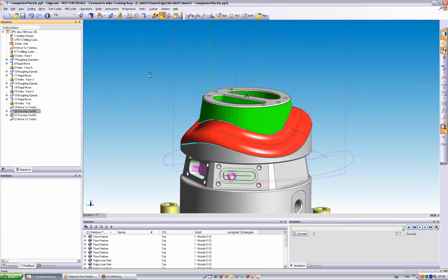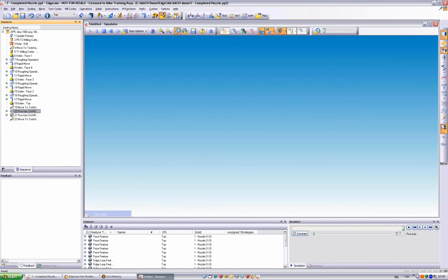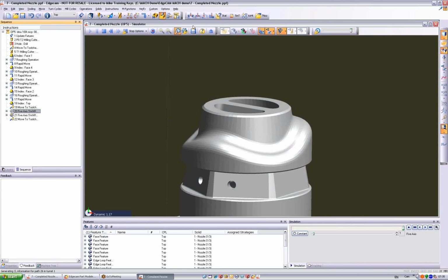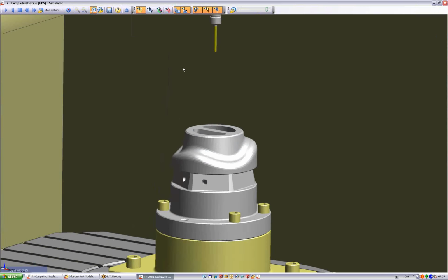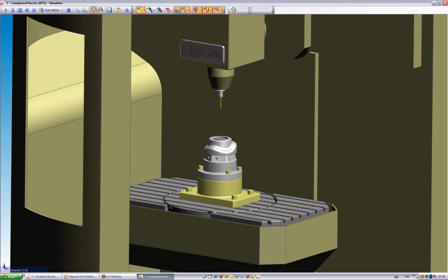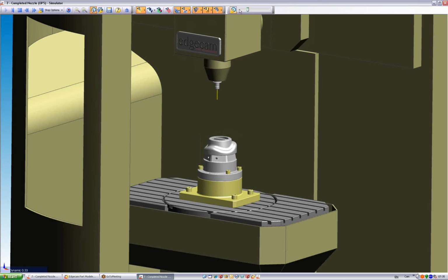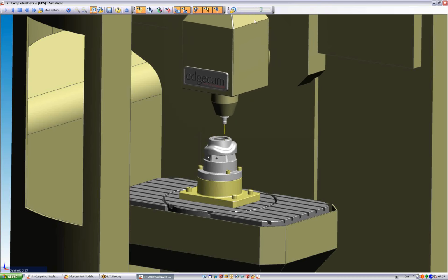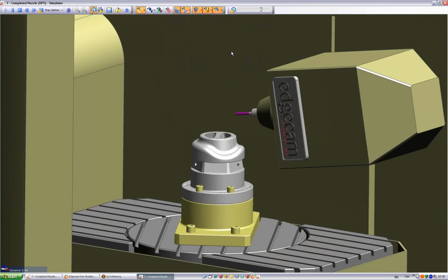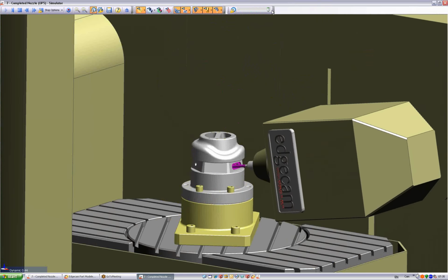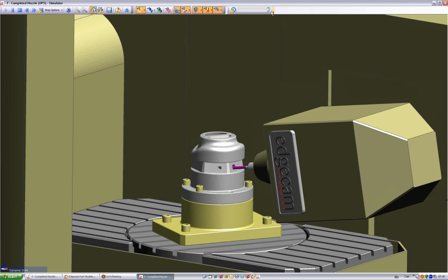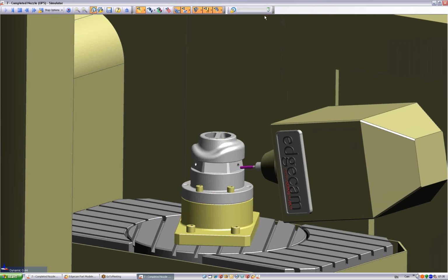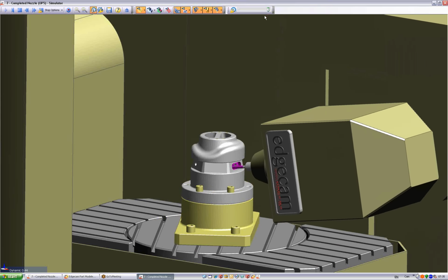And again, we'll just conclude because obviously machine tool simulation is extremely important, again, to make sure that all the machine tool members, indexing, 5-axis, drilling, profiling, roughing, all these need to be simulated, all need to be gouge checked, all need to be collision free before we can confidently move forward and produce a CNC tape.